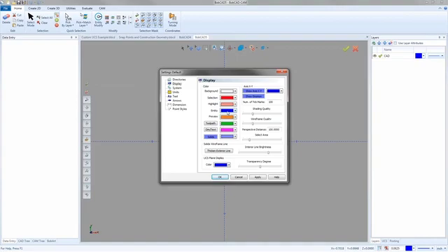The toolpath is going to show up as this dark blue, which for me is one of the most annoying things in the world because I can't see what's going on anymore. Right here, though, if I turn on the toolpath button, just click that button on, now whenever I calculate a toolpath, it's going to show up as this bright green. You could change that to whatever color you want. The only trick is just make sure that the toolpath button is clicked on. The dim text one right below it is clicked off. And that's the same thing.